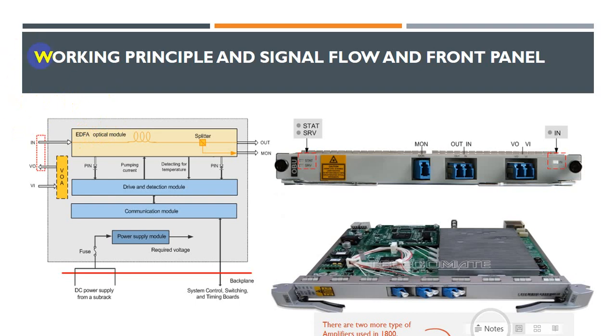Any optical wave we give to this amplifier, it amplifies the signal, with the gain of 23 dB fixed as I told, and sends it out. For monitoring the health, we can have a spectrum analyzer or board analyzer. This is a monitoring port, which is 1% of the main signal. So 99% of the signal goes out here, and 1% is here for monitoring purposes.